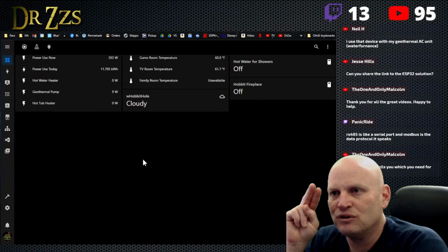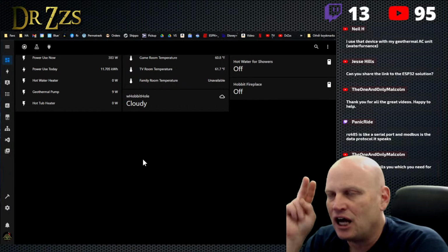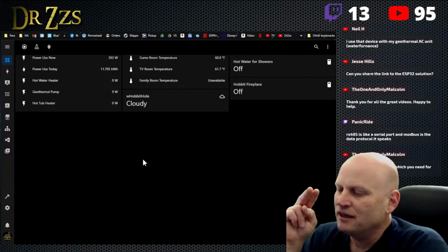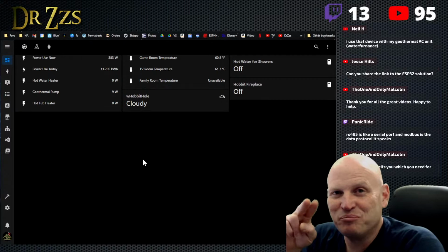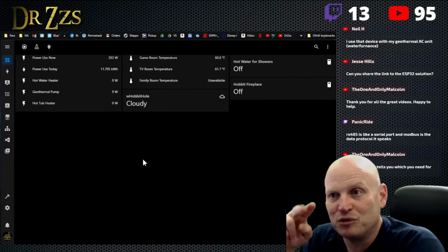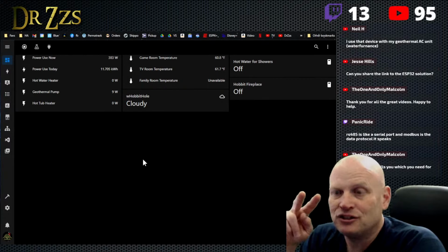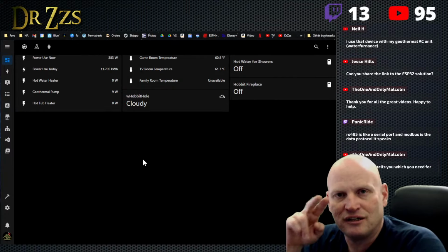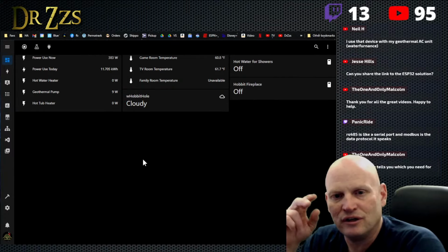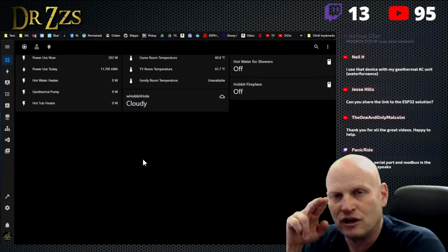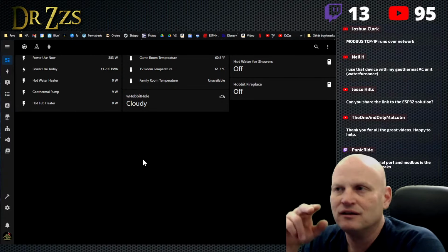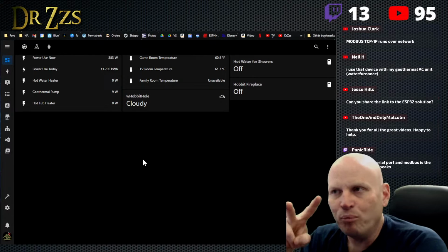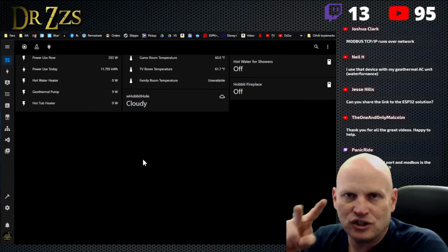So I've got it set to an auxiliary, I don't know, an extra port that the inverter makes available. That's got a relay that's just open-close contacts, and I've got the generator set up so that if you open and close a wire, it will turn on, turn off. Right? You close it, turns on. Open it, turns off. Great. But so far in 2 tests, the open of that relay has not functioned properly.